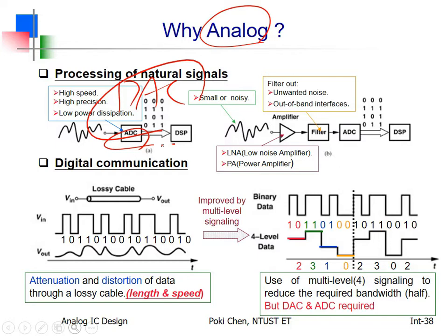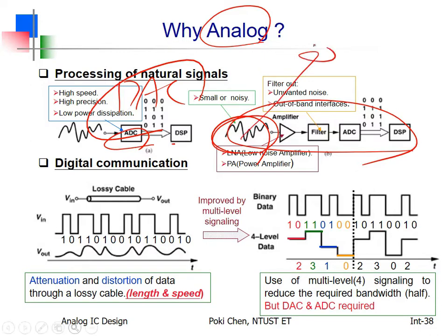And then this is another application, just like our mobile phone. You can see this is for the receiver. In the air, we have an RF signal. But how large is the signal? I'm talking about the magnitude. Actually, that is on a scale of 10 to the -6 order in volts. Can you enjoy such a signal? No, too weak. So we need to amplify it.